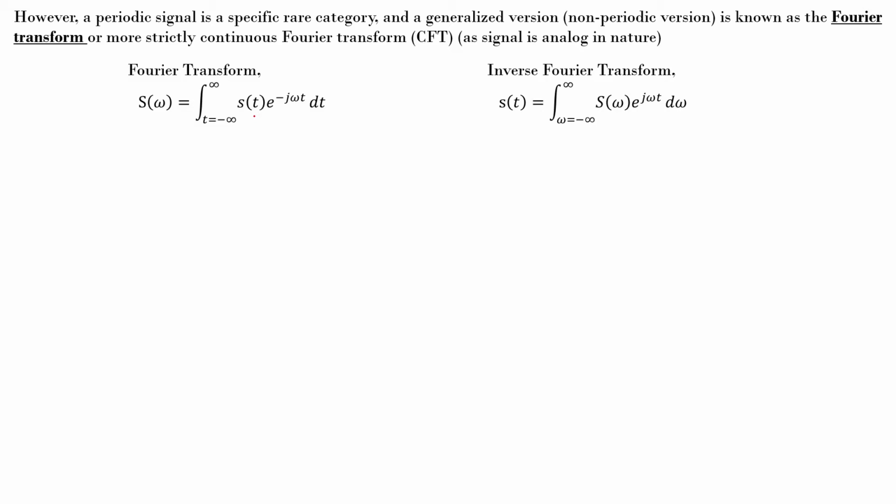You are not going to shift the signal left and right. It is at t equal to basically 0. Sorry, tau is equal to 0. In your correlation expression, you have a shift term, right? That term is 0, so this is like a 0 lag correlation. So you're going to correlate your signal with a particular frequency component, and that value is basically your Fourier coefficient.